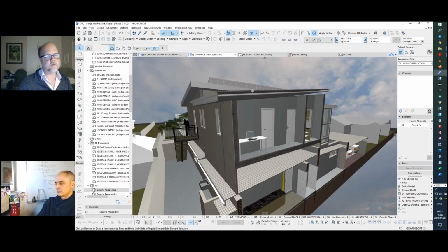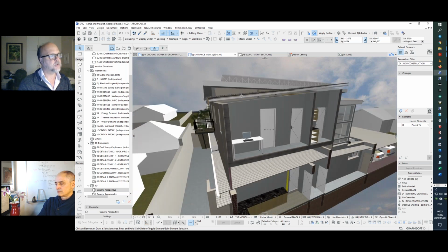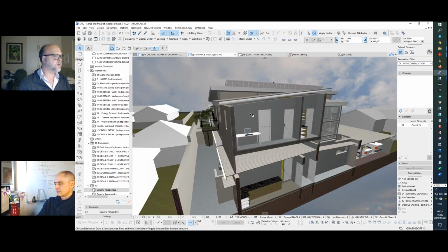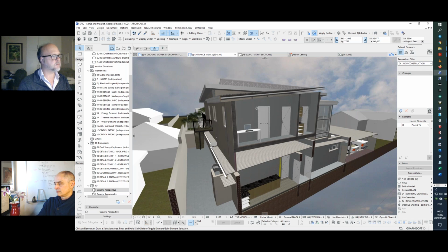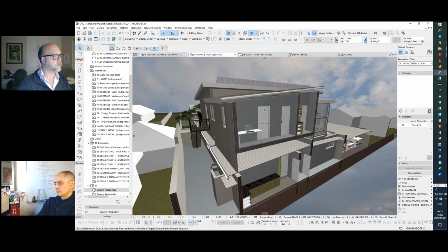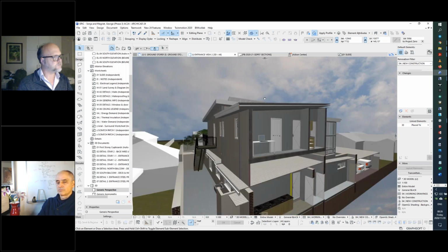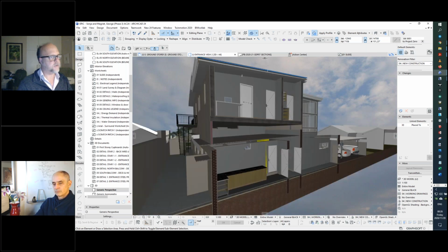These panels don't need any structural support over a distance of 7.5 meters with a polystyrene core of 75 millimeters. So no structural beams, rafters, purlins, nothing needed for the structure of the roof. So does that give you the picture that you were looking to see? Yeah, yeah. No, I think that's great.